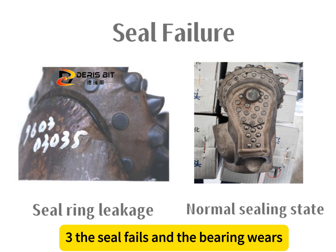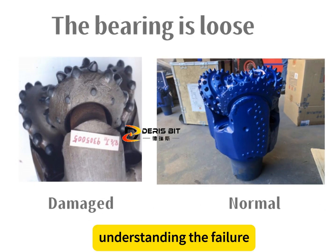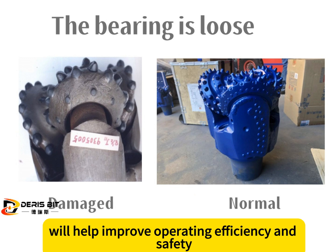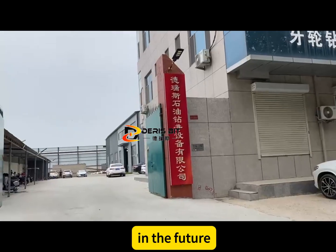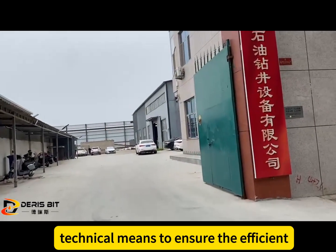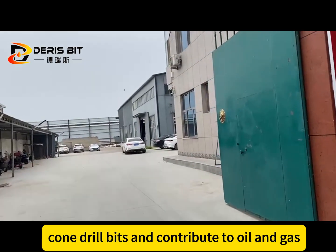8. Bearing looseness. Due to the failure of bearing locking and the wear of the cone shaft hole, the bearing loosens. Main reasons: 1. The locking steel ball breaks and falls. 2. The retaining ring breaks. 3. The seal fails and the bearing wears.